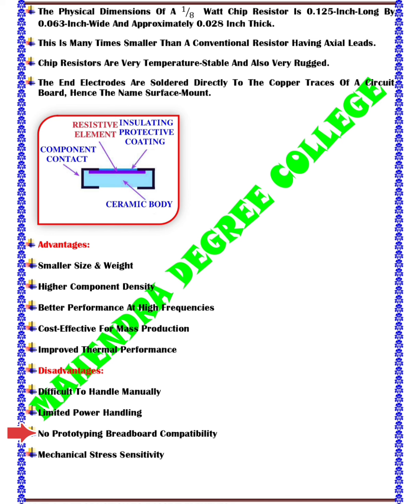Third one. No prototyping breadboard compatibility. It means surface mount devices are not readily compatible with standard breadboards or prototyping boards, which typically accommodate through-hole components. This limits their use in early design stages or for experimentation.